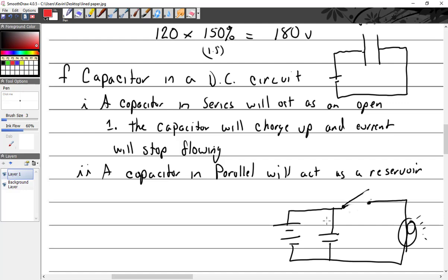One of the things that you're going to be talking with Phil about is capacitance discharge ignition systems and the potential to get knocked on your butt. You guys have had that class. Oh, yeah. So what's the deal with those? I don't know. Some other semester. Hey, one week at a time. You have to discharge it, make sure it's locked out, no one turns it on while you're working on it. It says igniter box, right? Yeah. Why? Because it'll kill you.